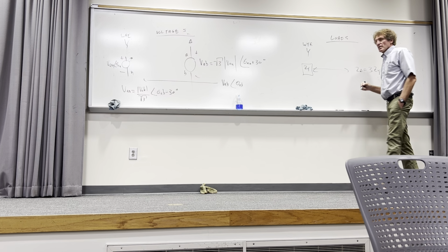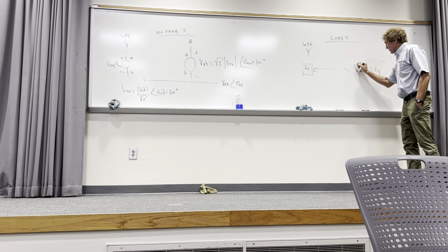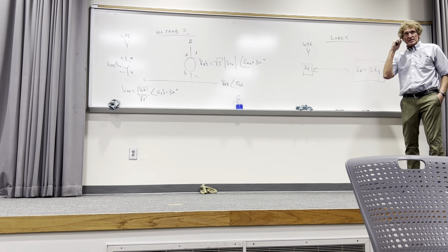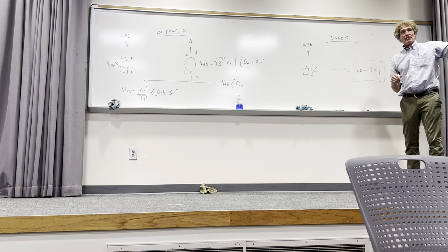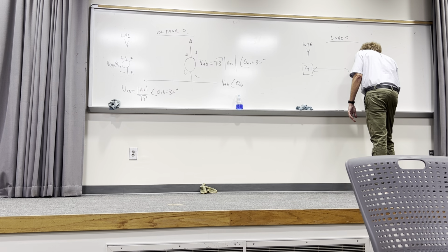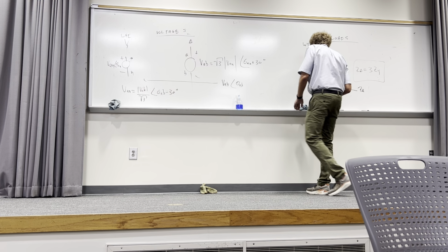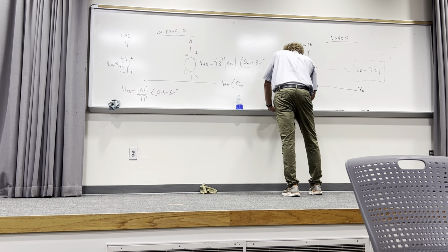You don't have to worry about phase. It's that simple. Take 3 times it. Y'all with me? Can everybody see this in the back, by the way? Far back. All right? And if you had Z delta, and you wanted ZY, ZY would be simply Z delta over 3.